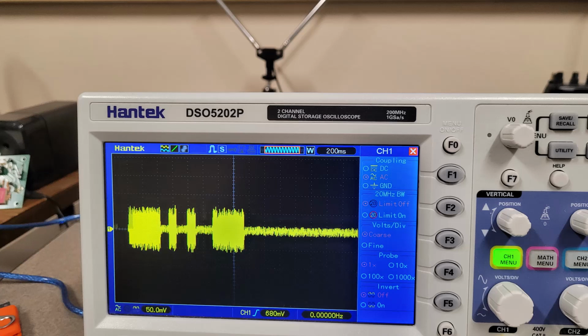Oscilloscopes just cannot handle that much power. So every time you're going to input your waveform from your transceiver, you need to make sure it's an attenuated RF output of the transmitter. Cut that power level way down, and you'll still be able to sample that waveform on the oscilloscope. So the answer is the attenuated RF output of the transmitter.